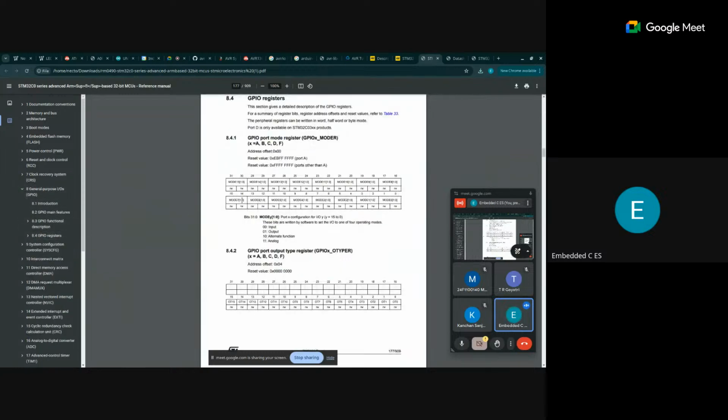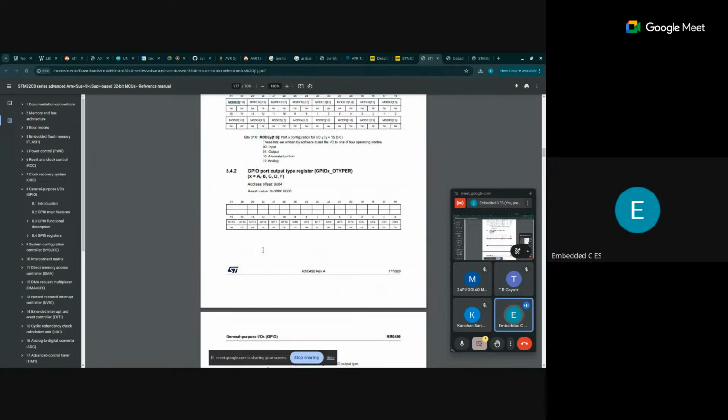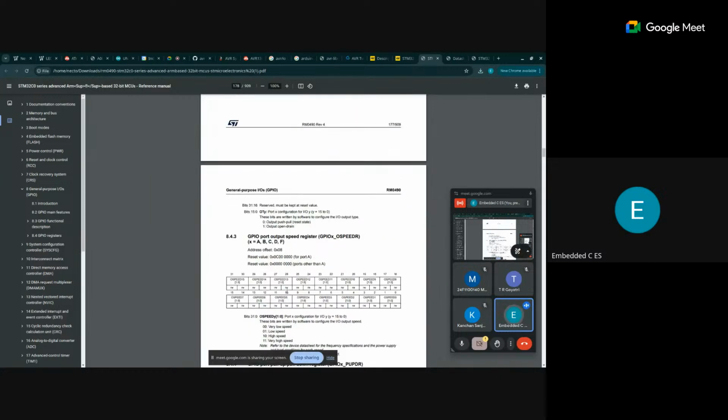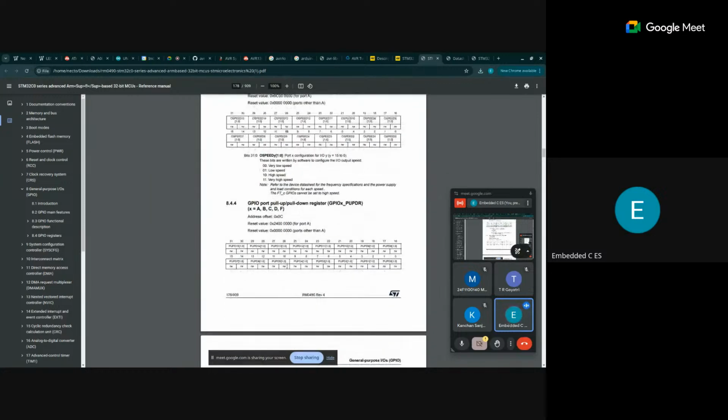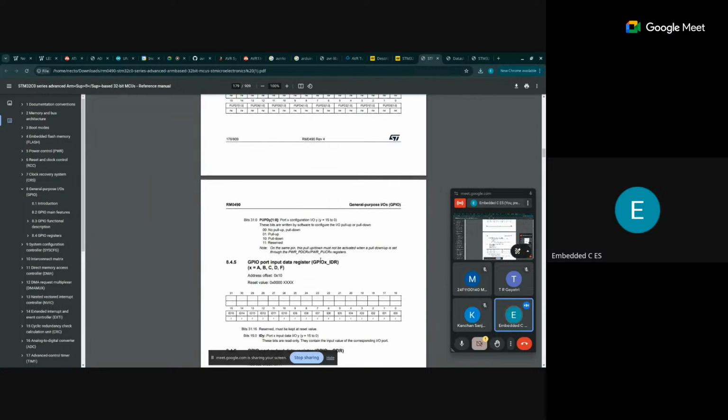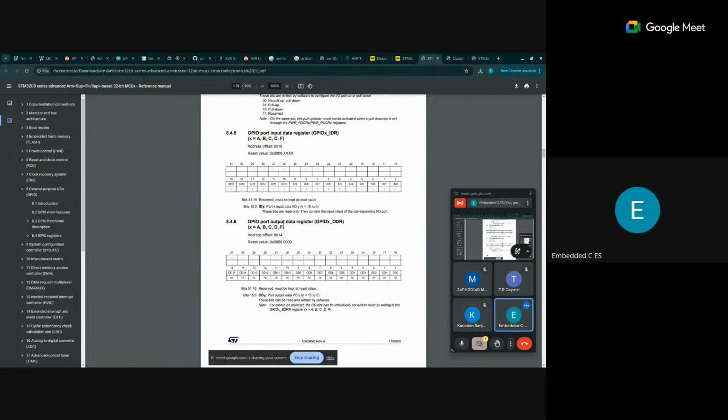This has the registers. You see, for GPIO, there are these registers. So GPIO here is kind of more complex than the GPIO in there. You can see different mode bits and the output bits, output type bits, speed bits. So it can operate at different speeds, pull-up and pull-down registers, PUPDR registers, and the GPIO IDR input data registers.